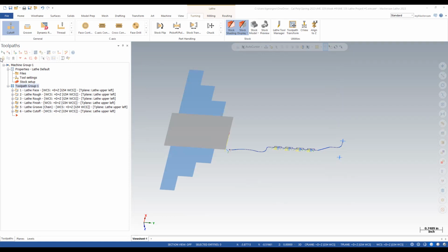Now, look at that. T101. We're doing good, right? No tool change. It's not supposed to. We learned about that. G18, we learned about that, right? G18 plane. So G97, it starts it up to 1400 RPM. I don't know where it gets this number at first, probably where the diameter is. And it rapids to the start point. Then it turns on the spindle speed clamp and then turns on G96. So this post always starts at an RPM first. You don't have to do that, but it's the way it works. Then G99, all of our F values are our chip loads.